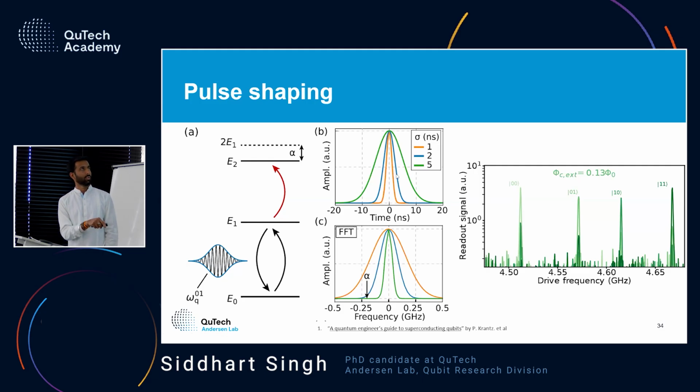Yeah, but if you look at the curve here, this is for 1, 2, and 5 nanosecond, and this corresponds to frequencies already 250 megahertz here. But in our case, the first spread is a difference of 50 megahertz, then less than 50 megahertz, and then the overall span is 150 megahertz. So we do not have a big frequency span to play with. So the leakage starts happening around 24 nanosecond, 30 nanosecond is where we see already the errors have gone very high.